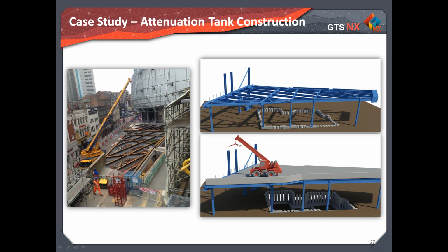The research case study relates to the 4-meter deep excavation works required for the construction of an attenuation tank at the Birmingham Snow Hill Station redevelopment project. The attenuation tank was to be formed using contiguous CFA piled walls with base and roof slabs, which you don't see here but will be shown later. The slabs act as a truss in permanent conditions.